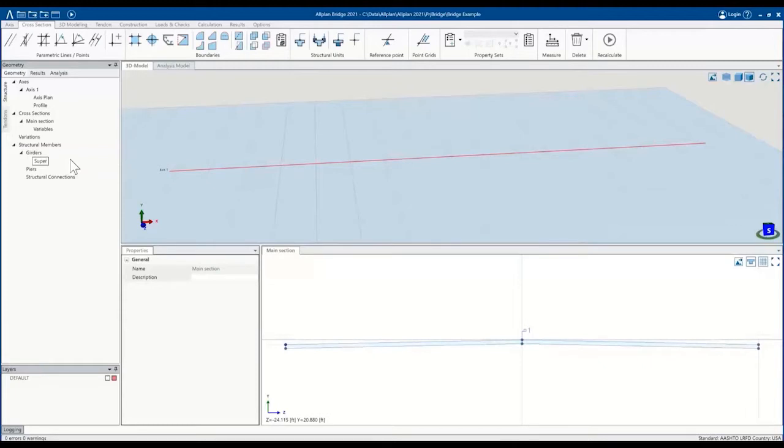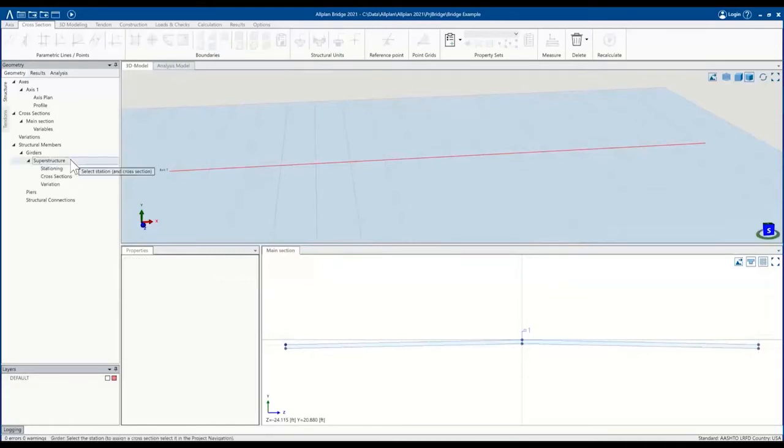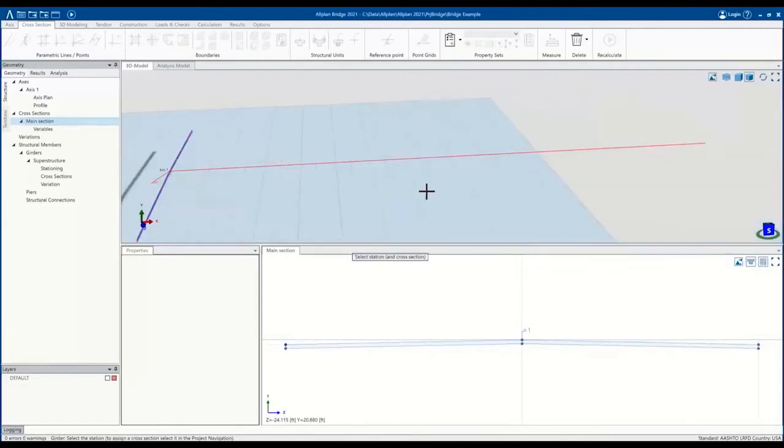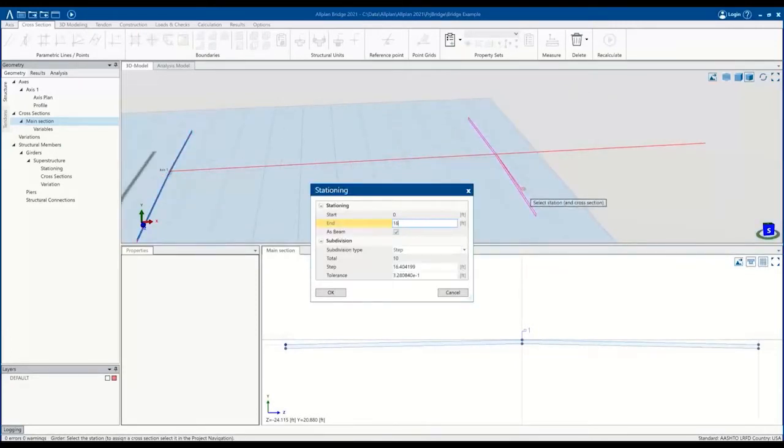And as David was explaining that, I was able to finish off a deck cross section. And now we'll go ahead and apply that cross section to our alignment to create our deck itself. So the way it works is we'll define the beginning of bridge. You could click anywhere, and then you have a dialog box that comes up where we could tie in the exact station location. And for the first segment, we want to go, let's say 160 feet.